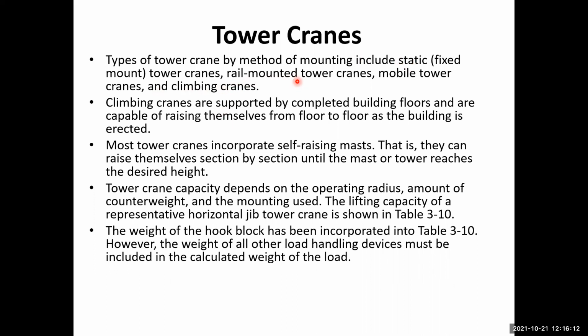The climbing cranes climb up the building as the building progresses from one story to another, to the third story, to the fourth story, etc. The climbing cranes are supported by completed building floors and are capable of raising themselves from floor to floor as the building is erected.